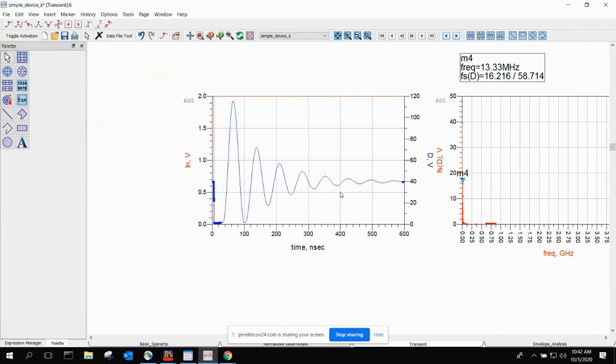You could have an S11 or an S22 that's outside of the Smith chart and still technically not have a self-sustaining, self-starting oscillation. Now, I'm not sitting here telling you that it's a good idea to design that. In fact, I think it's a horrible idea to design a circuit that does this sort of thing. I'm simply pointing out that the rigorous metrics you're deriving from this probe are designed to detect self-sustained right half plane poles in your transfer function. This is not one of those poles. Technically, this circuit is stable. The rigorous metrics are right here, at least in this particular case.